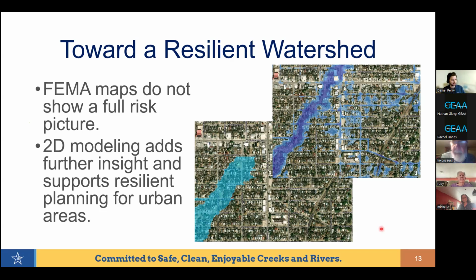And so again, this is a good example of the differences between 1D and 2D. In 1D, you have this single floodplain that was identified previously, so we build our models off of that floodplain specifically. In 2D, your project area can go all over an entire subbasin or watershed, so you can start seeing floodplains and where the flooding is mainly coming from.